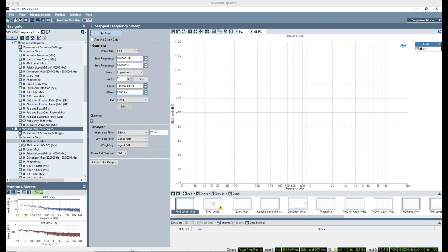Does the system cope with any changes of the reference speaker that occur between equalizations, or do you expect the reference speaker to remain stable? So the system does not automatically do anything. It is assumed that the reference speaker is stable. As anybody who works with speakers knows, that might be a bad assumption. So two things. I myself always equalize the speaker and calibrate the speaker when I'm starting a new test session.